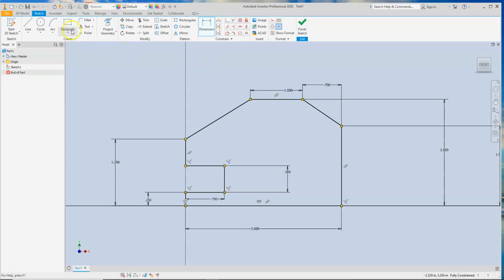The only thing I'm missing now is the circle. So I want you to get out of your old AutoCAD habits, as far as maybe drawing a line over and up to locate the circle. Feel free to just come over here and sketch the circle right there in the middle. Just pick a point and then we're going to locate it X and Y. Something different in Inventor is that we have to specify the diameter, and all circles are drawn with a diameter, so you can lay that out with a diameter dimension given.